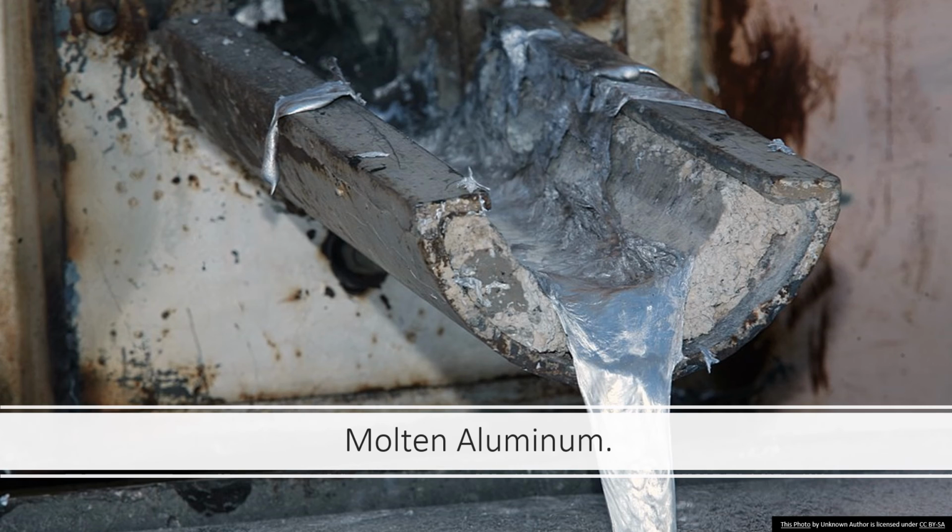As the metal moves through the mold, the exterior is cooled with water, causing the aluminum to solidify. The solid shaft emerges from the far end of the mold, where it is sawed at appropriate intervals to form ingots of desired length. Like the smelting process itself, this casting process is also continuous.